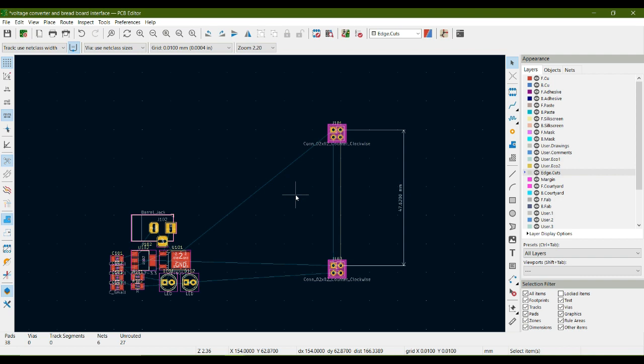So today we have learned how to open the PCB editor, how to import footprints, and how to create a specific distance between two components and place headers at a distance of 47.62 mm, which is our breadboard requirement, so that when the PCB is final and printed, we can easily insert these headers in the breadboard.